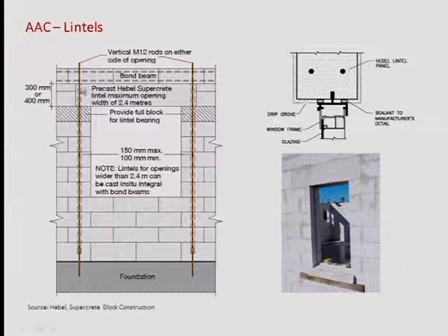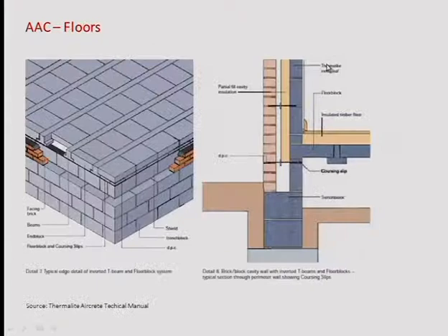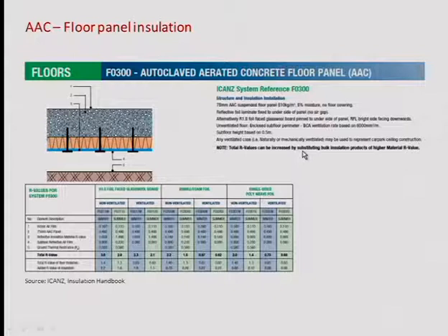Okay, also you see the lintels, how they are reinforced. This is the cross section through the lintel. Just out of curiosity, you can also make floors out of it. They're not very used, but you can have these T-shaped elements and then other blocks that actually generate the floor. And you will see also the R values. You see they're much higher than the previous ones.